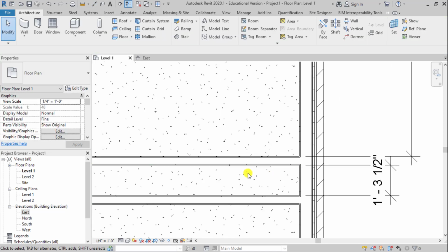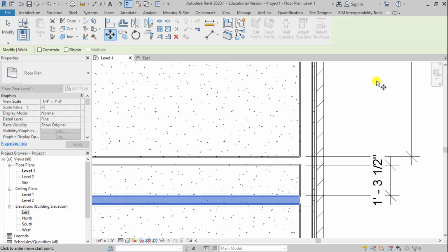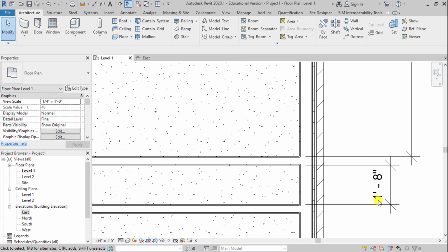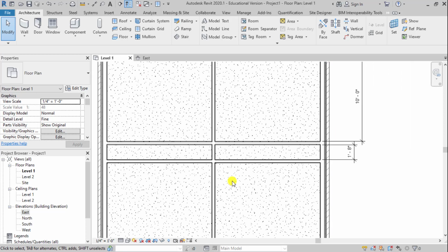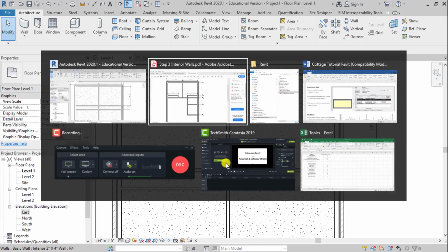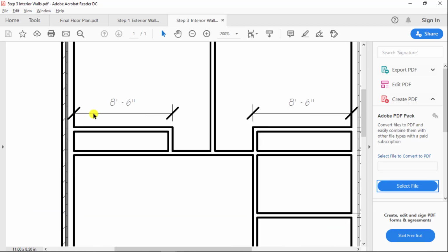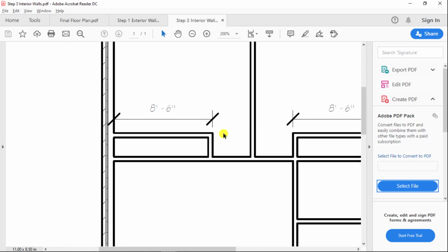And it's small because we did not account for our wall thickness. So if we do a real quick measurement, use the measure tool to go from this face to this space, we see that our wall is 4.5 inches. So this wall here needs to move down 4.5 inches, which is our quote mark. We've got to put that inches in, otherwise it's going to move at 4.5 feet. So now we're at 1'8" for our closet depth, which is good. And we know that we need a 8'6" closet length on both sides.